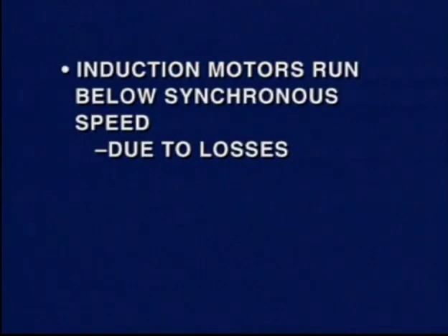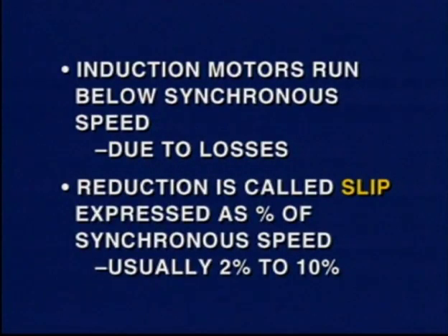Induction motors run below the synchronous speed because of losses in the motor. These losses occur because the rotor lags the stator's rotating magnetic field, therefore rotating at a slower speed. This reduction is called slip and is represented as a percentage of the synchronous speed. In fact, slip is necessary for an induction motor to operate and provide torque. Most motors run at between 2 to 10% slip with no load.